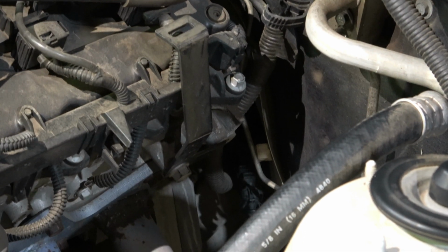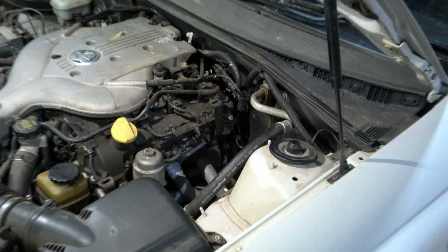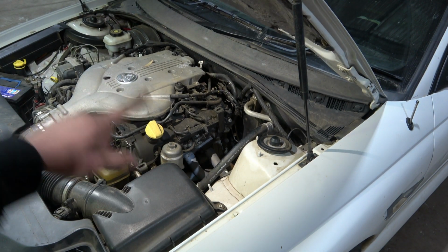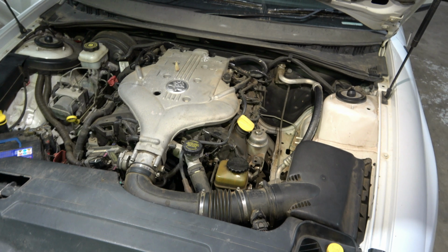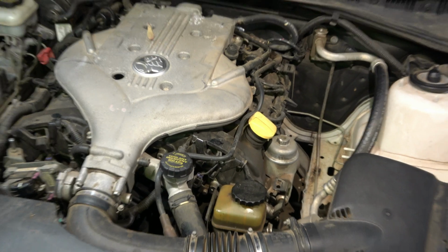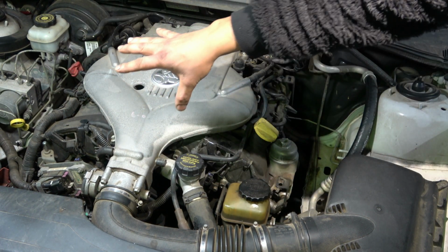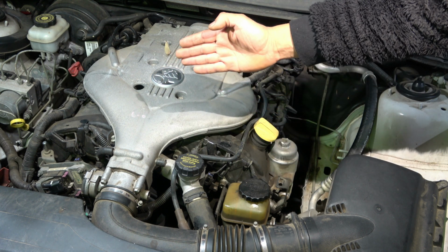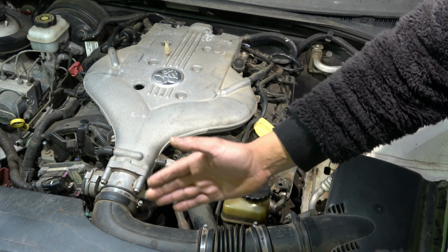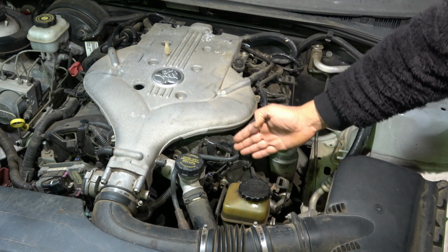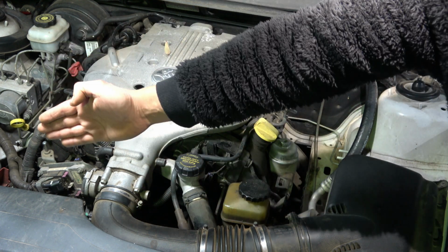Okay, so on this engine, bank 1 sensor 1, bank 2 sensor 1. So bank 2 is this side, bank 1 is that side. It's very easy to identify which bank is what just by looking at the engine. I'll quickly show you how to know which bank is what. If you look at the front of the motor, look at the tappet cover. There are going to be 2 tappet covers on a V6 or V8 engine. The tappet cover which is sticking out further to the front of the motor is going to be bank 1. So in this case, this tappet cover is about there, and if you line that up with the other side, that side is sticking out a bit further.